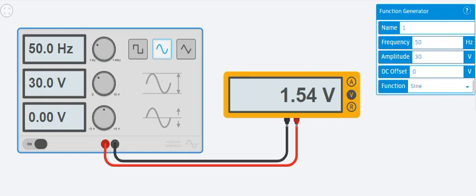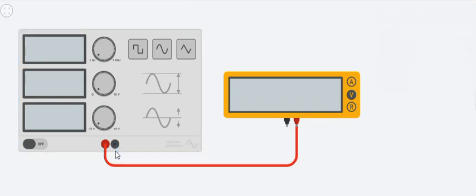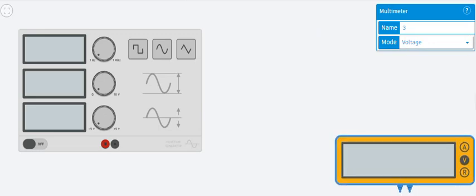So let's see what we can do. We are going to supply the voltage here. We're going to supply it through a diode. So by the time it passes through the diode, the output will not be a complete AC, although it will not be a complete DC as well. So there's a number of stages that needs to go before final. So let's bring in a diode.